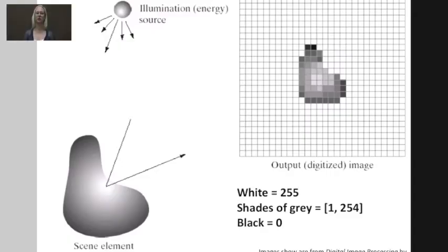Performing image processing on a piece of hardware like an FPGA can seem counterintuitive to those who use programs such as Photoshop. Since images coming into a computer system are originally real-life data converted into electrical data, electrically triggered hardware like an FPGA can complete the processing without having to reinterpret the data in a format readable by software. Images are a series of matrices full of numbers representing light at each pinpoint-sized area of the image. By doing specific combinations of basic arithmetic like addition and subtraction many times over different parts of an image, we can process an image without the complication of software.